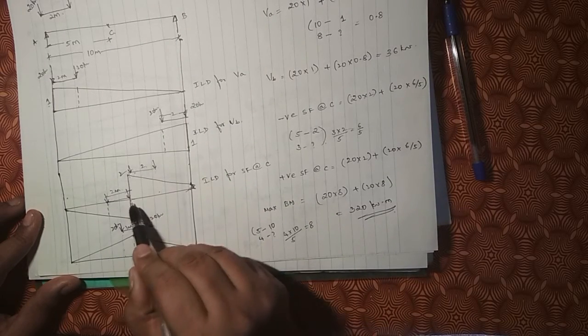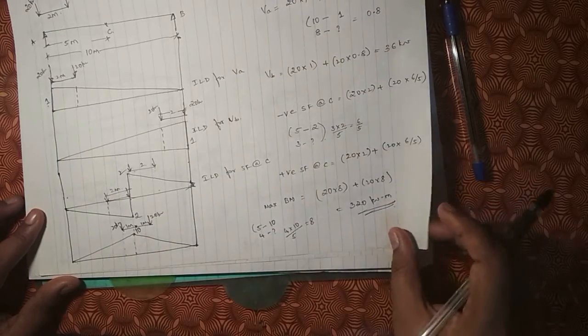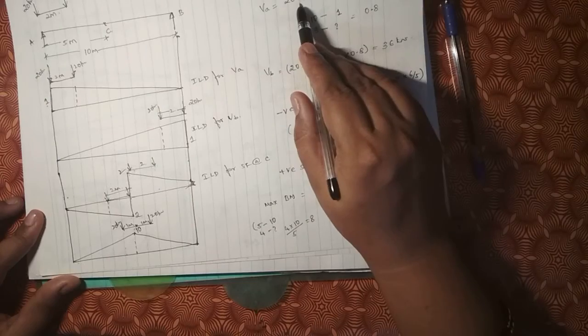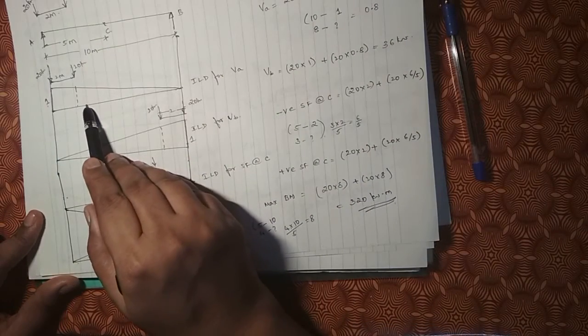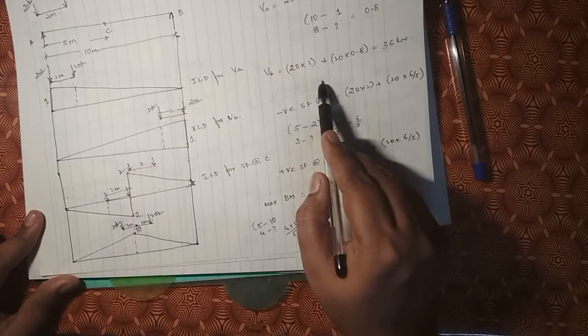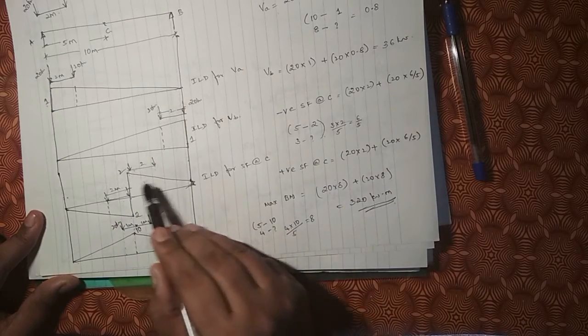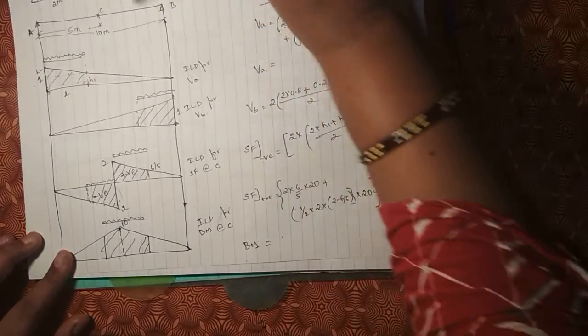Make sure how we have placed the load positions. Recollect the previous part and substitute the corresponding ordinates: for VA, the ordinates from the VA graph; for VB, the ordinates from the VB graph. For shear force, negative zone takes negative ordinates and positive zone takes positive ordinates. Multiply the load with the corresponding ordinates and you will end up with the solution.